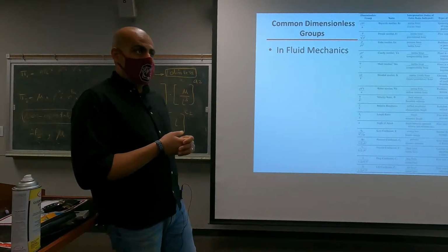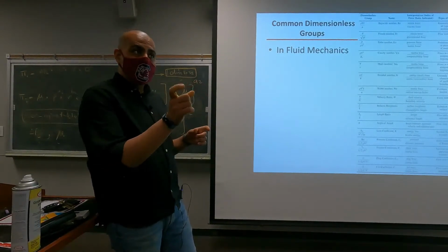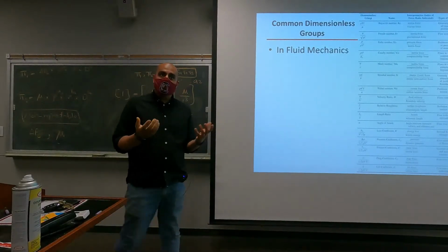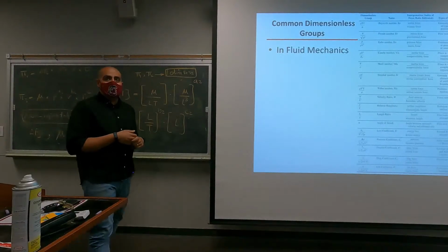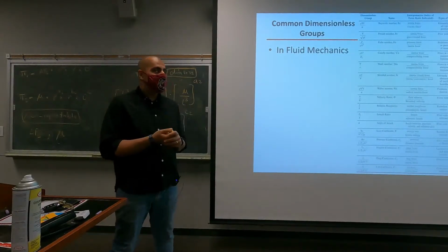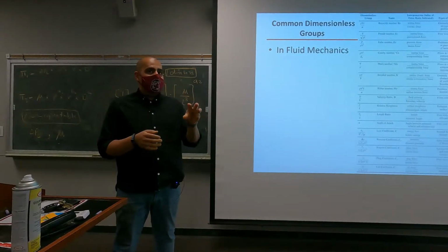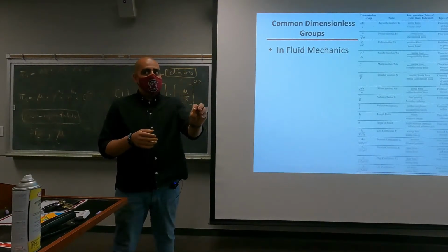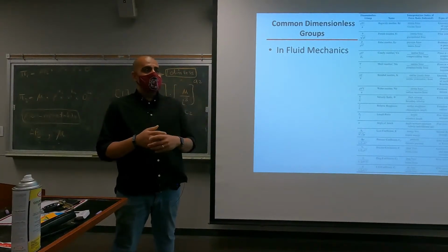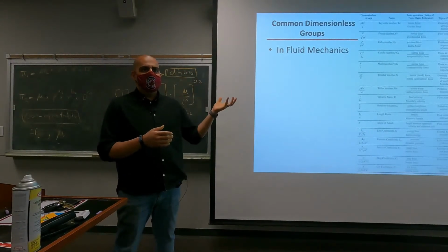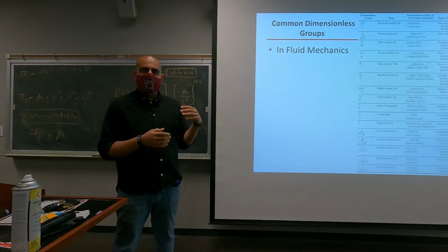That dimensionless parameter is something that we can apply anywhere. You can apply it to a very small test section inside a wind tunnel for an aircraft, for example, or you can employ it on a real wing, right? That's the beauty of dimensional analysis, that you can do the analysis for a very small wing in a wind tunnel, and then you can apply that same analysis to a huge aircraft, because you have removed all of the dimension dependence here.